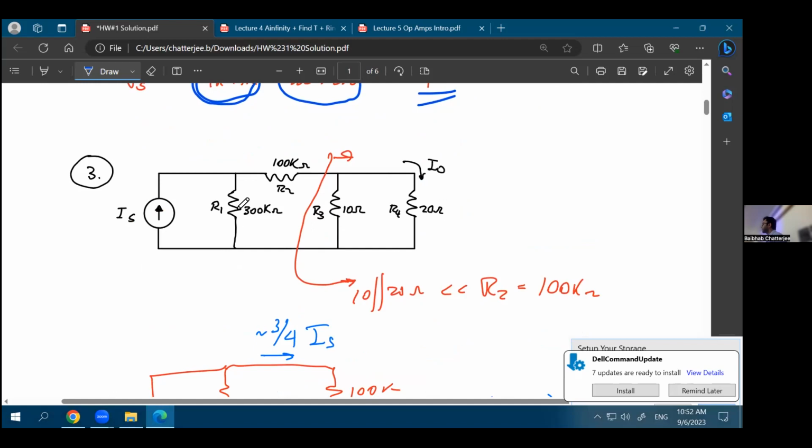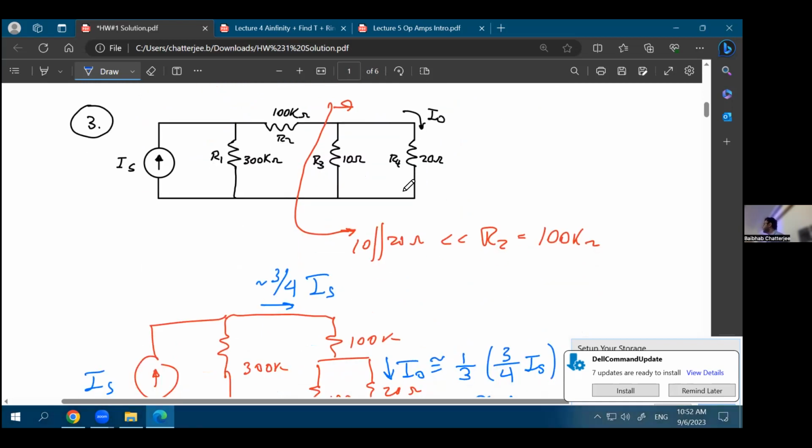Third one, it's a little bit different, but again, the same formulas and same theories apply. It's a current division instead of a voltage division. So just apply your current division formulas, which are a dual of your voltage divisions. Okay, and the approach will still be similar. You start at the output side and you traverse back towards the input.